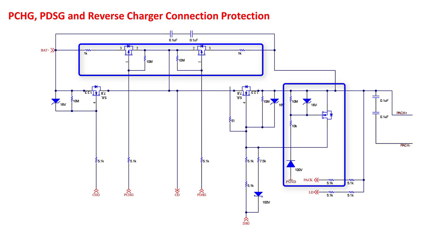For a battery with cells at undervoltage, charging can be done with reduced current with a series resistor until the battery reaches a programmable voltage level. Once this level is reached, the charge FET is enabled for normal fast charging, and the pre-charge FET is disabled. The pre-discharge FET can be used to reduce inrush current when the load is initially powered. If the pre-discharge feature is enabled, then whenever the discharge FET is turned on to power the load, first the pre-discharge FET will be enabled, and then transition to turn on the discharge FET and turn off the pre-discharge FET.